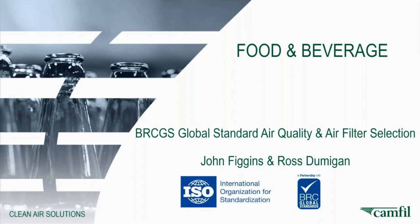Now, for many years, the BRC Global Standards have contained requirements for air quality. For example, in clause 8.2.2, there's a requirement for high-risk areas to be supplied with sufficient changes of filtered air, and the filter specification and frequency of changes of those needs to be based on a risk assessment, taking into account the source of the air and the need for positive pressure in those areas.